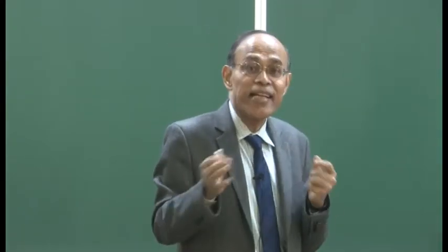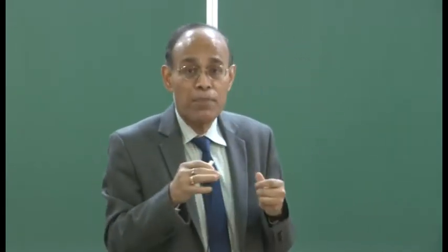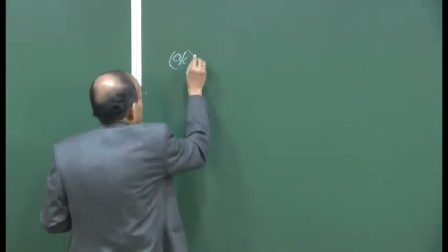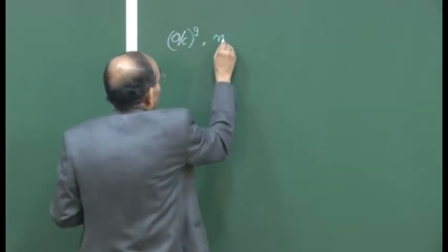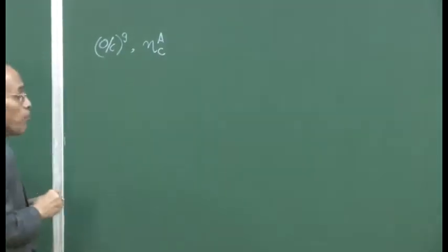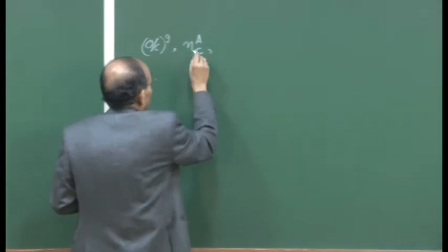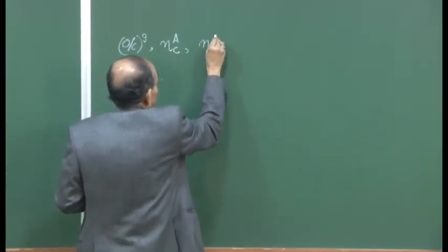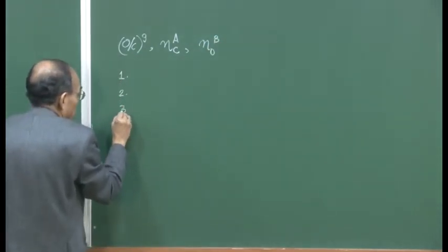And as I had indicated during my first lecture, we would like to have a fully predictive model. So, therefore, for the three unknowns that we desire to seek in this exercise, the top gas composition or the O/C ratio in the carbonaceous portion, the active carbon rate or the coke rate of the furnace, as well as the blast rate, they could be expressed in terms of three different equations.